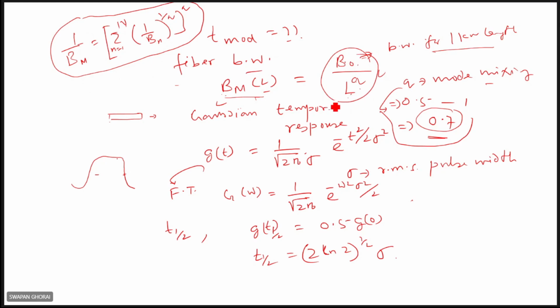Next, that is not sufficient. You have to determine the modal dispersion lifetimes if you know the full width at half maximum. Let us see how it can be calculated from this fiber bandwidth. Only if you know the full width at half maximum can you find out the fiber modal dispersion. So for that, suppose you have launched power within a fiber, and the output of the fiber, we assume, is Gaussian. It is a Gaussian response.